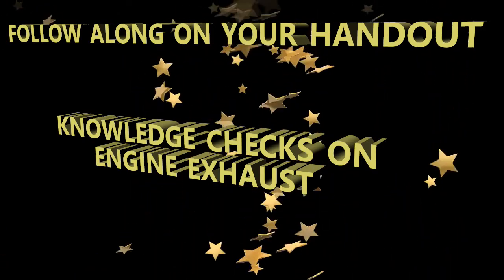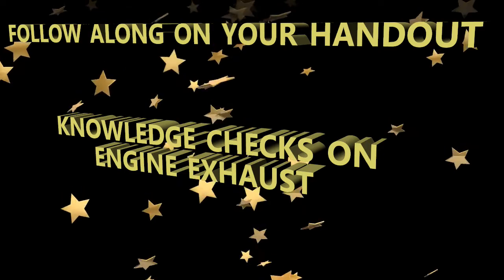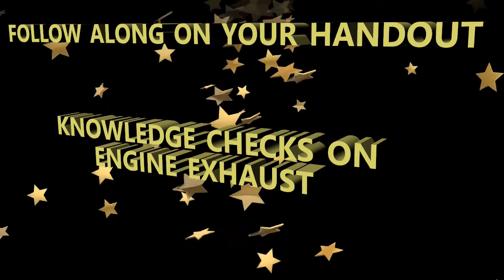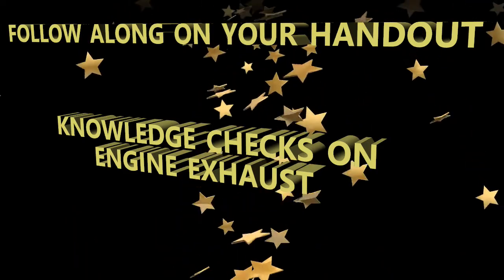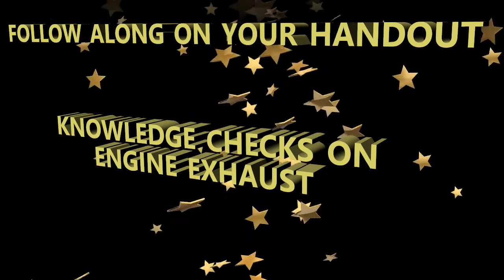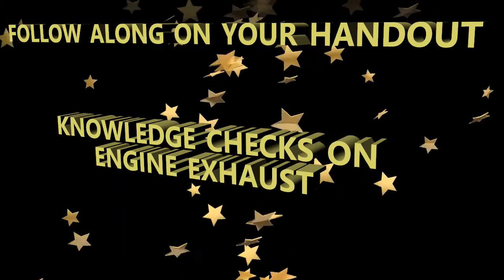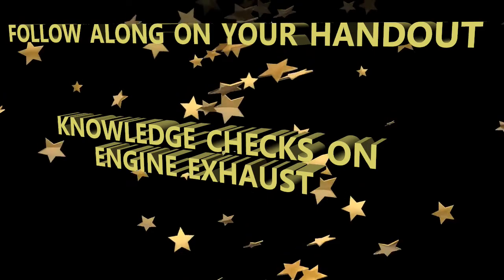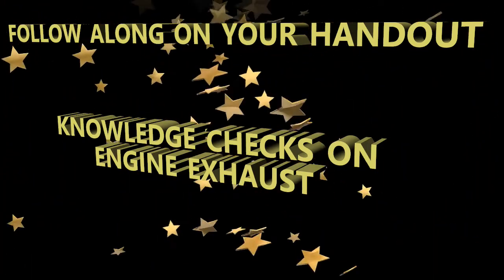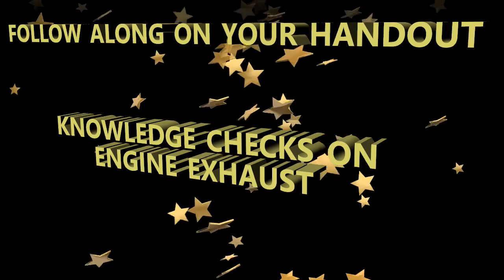All right, number 20. What must you ensure first before doing a thrust reverser operation test? Okay, is it the directional valve is open, or the AMM, your aircraft maintenance manual, specific circuit breakers are closed? I mentioned the circuit breakers. It's important you close them. That would be number 20. Otherwise, you're not going to have an operation. You've got to close the circuit.